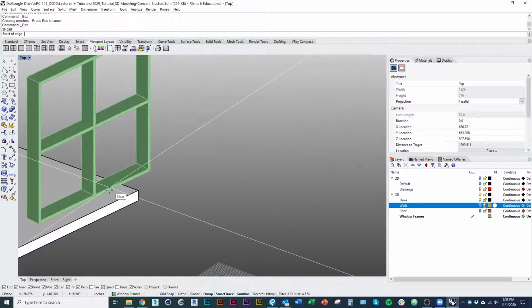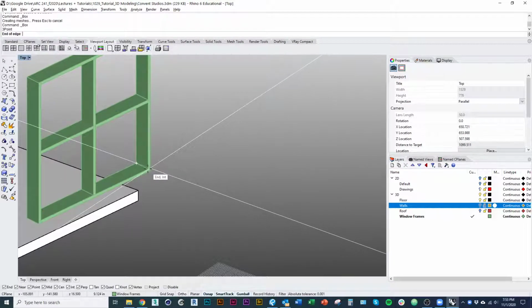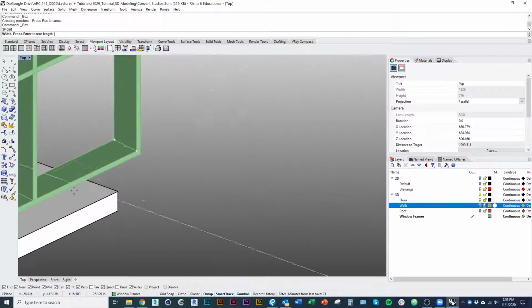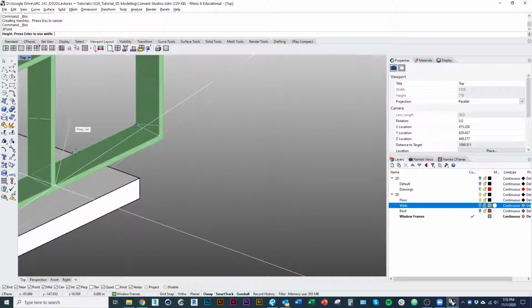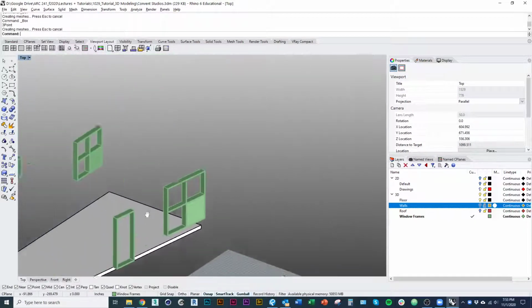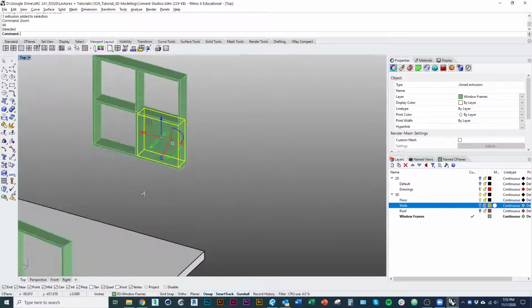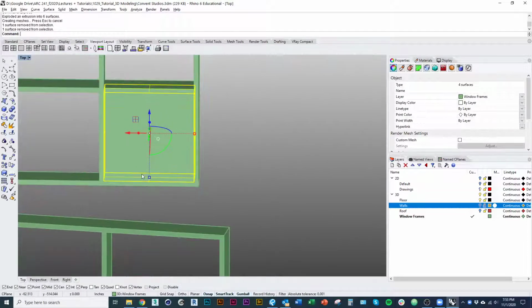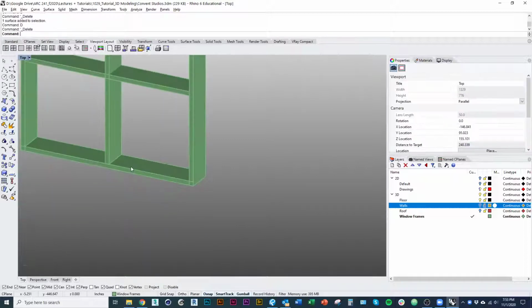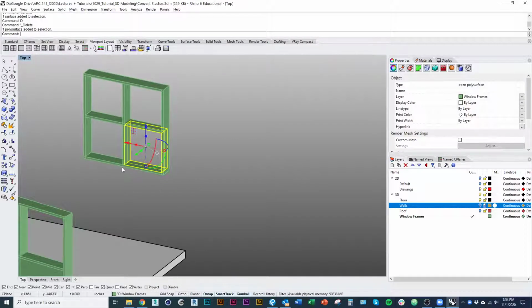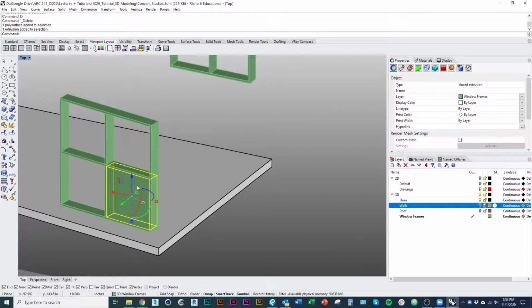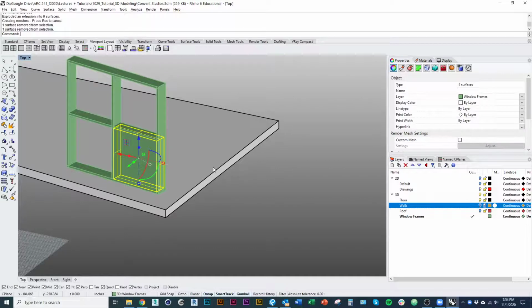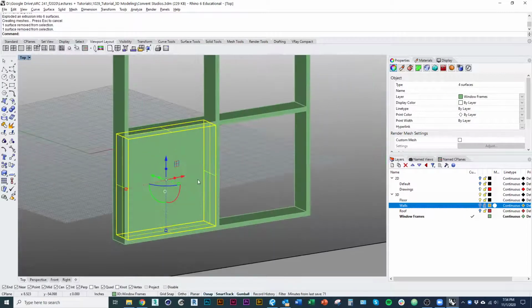I'm going to start with 3-point on this guy because remember this wall is tilted. Tracing out that interior volume. Great. Explode. And then deselect the planes and join the outside. So now I have a surface that's that inside that I want. One more time, explode. I'm holding control and I'm clicking on the two flat faces to deselect them.